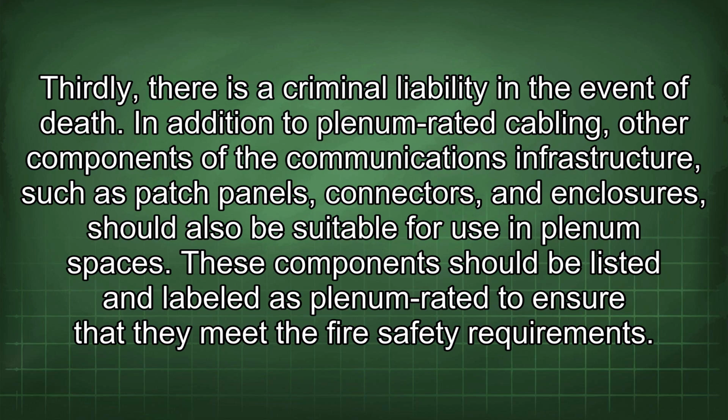In addition to plenum-rated cabling, other components of the communications infrastructure, such as patch panels, connectors, and enclosures, should also be suitable for use in plenum spaces. These components should be listed and labeled as plenum-rated to ensure that they meet the fire safety requirements.